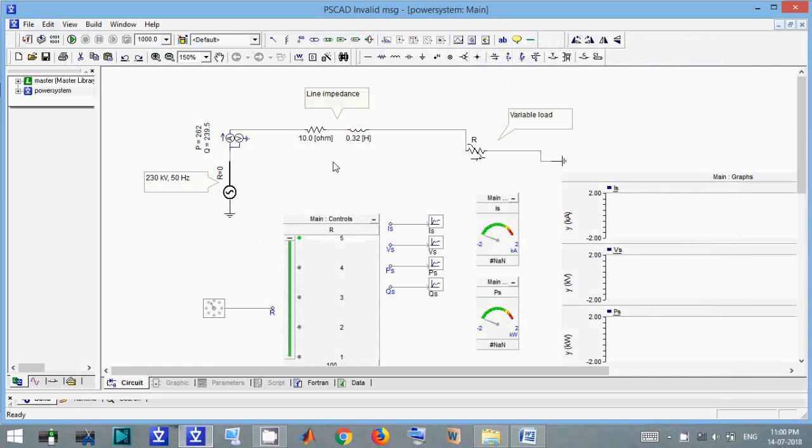In this model, this R and L is an equivalent transmission line, but there is a transmission line available in the PSCAD master library, so we will just replace these things, because in fault analysis you cannot mention the fault length from here. Okay, so you have to insert a transmission line.